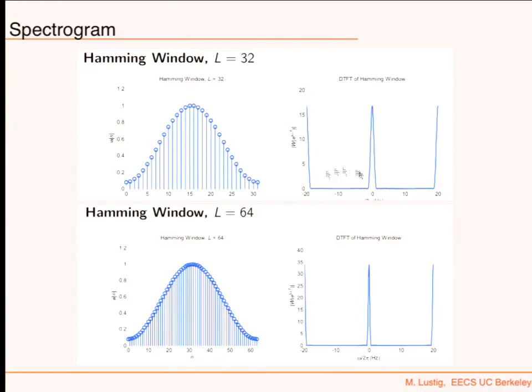But basically, any single frequency that exists in the frequency domain, when we use this window, is going to be blurred by this spread function, because it's going to be convolved by it. Okay, that's why we lose resolution. So it's also called a point spread function, which is really kind of an impulse response. In this case, it's an impulse response in the frequency domain. So I don't want to confuse you with these terms. But a point spread function is how a point or a single frequency would be spread, and so I get some uncertainty. Okay. All right.